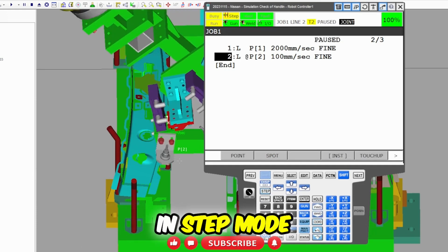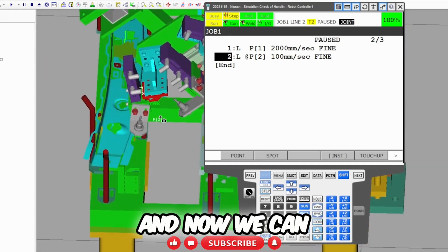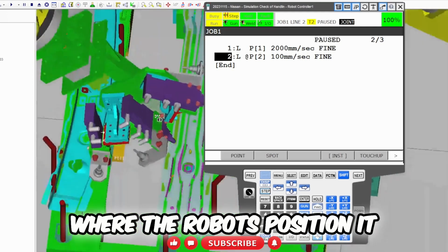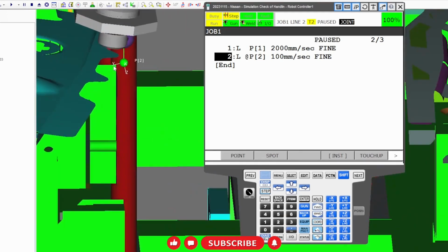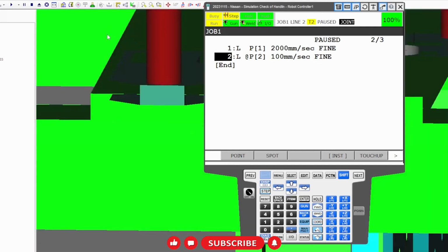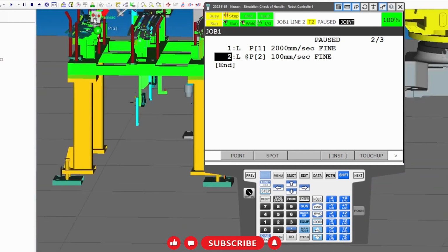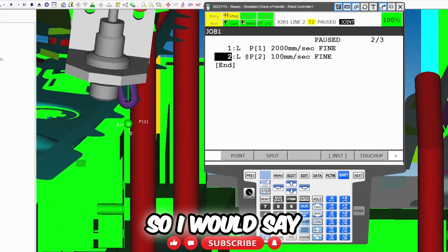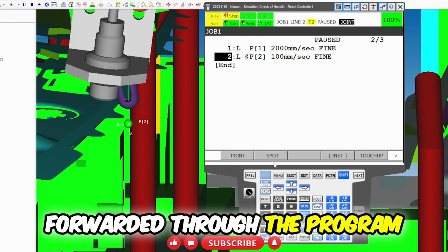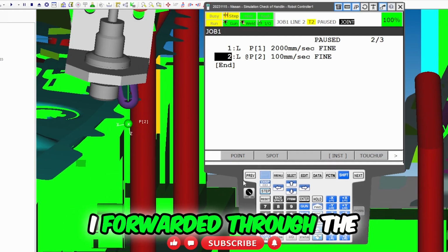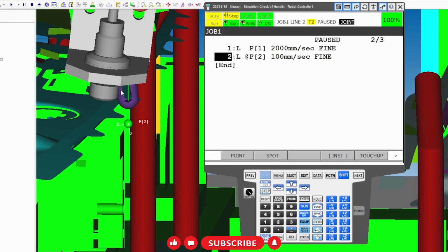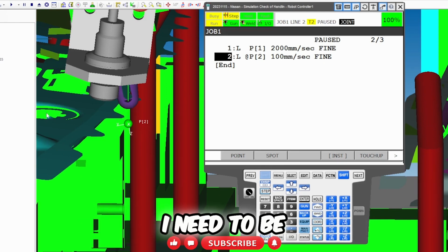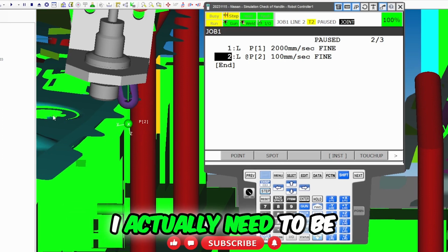So I just put it in step mode, I jogged the robot down, and now we can look at where the robot's position is. I would say the word for this is I just forwarded through the program and I tested the position that I just wrote. So now I'm just looking at that. I need to be over here. This position is completely off from where I actually need to be.